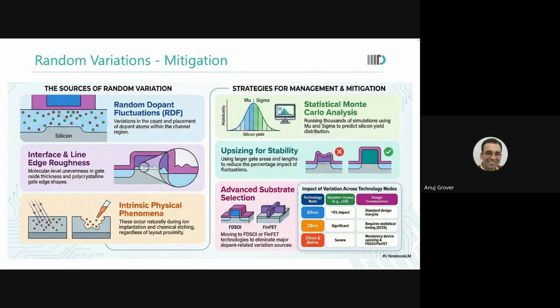Okay, so what does writability of a memory cell require? When you do write margin analysis, you find that nominal minus 6 sigma is minus 50 millivolts. What that means is that your bit line should carry minus 50 millivolts on it to be able to successfully write inside that particular memory cell. Are you with me? So the bit line capacitance is not a consideration for us.